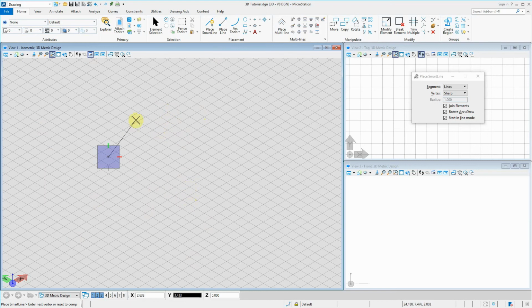This is where there are a few shortcuts that allow you to create and align this tool. If we press T, for example, you see how it rotates so that it allows us to draw in this direction, aligned to the top view. If we press F, it's now drawing in accordance to the front view. If we press S, it becomes the side view.